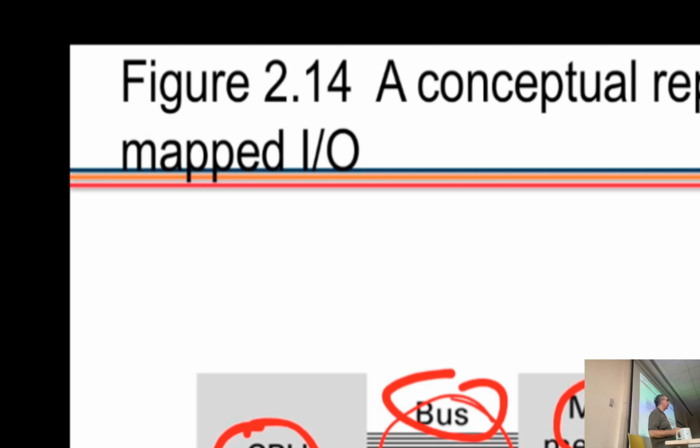not only the data, but also shows the address. So each memory cell has an address, like A0 to FF. Each of them is connected through another wire. So when I am trying to read A0, part of the bus indicates A0, meaning that I am reading A0, and this memory chip automatically is connected to A0.